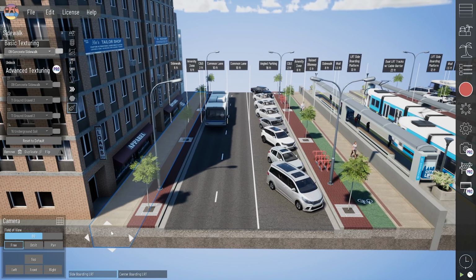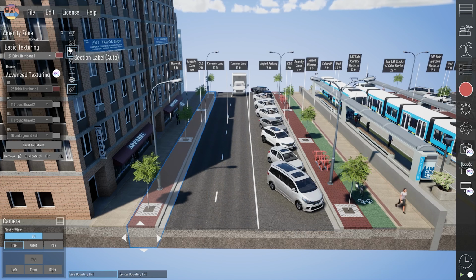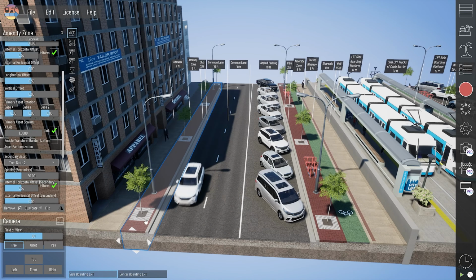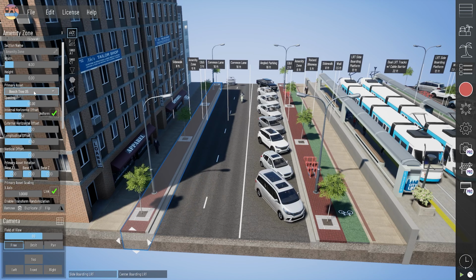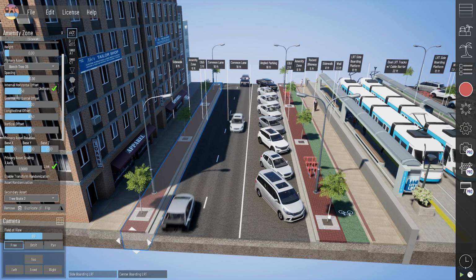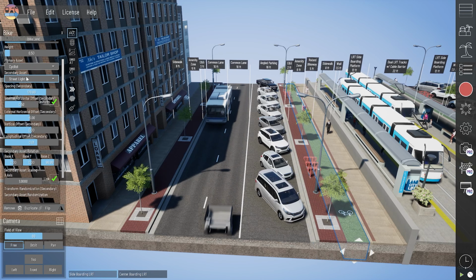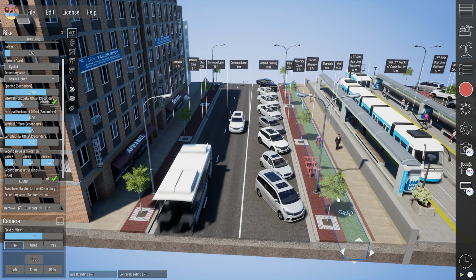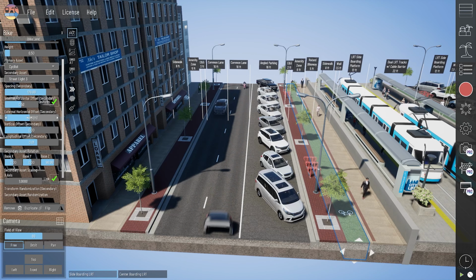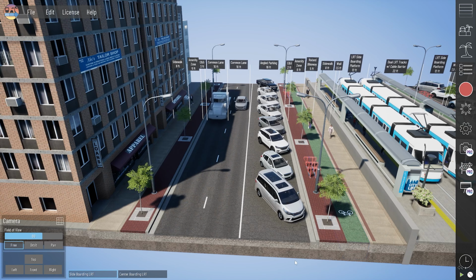We've got a sidewalk and an amenity zone, which is basically a sidewalk with a brick pattern. I will note that you'll notice we've got a few different repeating assets down this section. That includes our beech tree 5 and the tree grate. And in order to get those light poles into both of these amenity zone sections, I used the adjacent sections secondary assets. So you'll see here for the bike lane, I've got a secondary asset of the streetlight 3 and use the external horizontal offset to move that into the adjacent section.